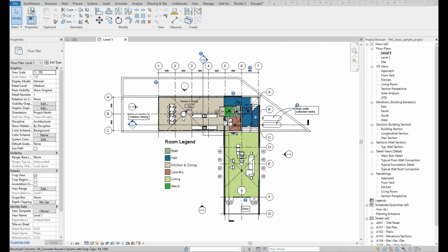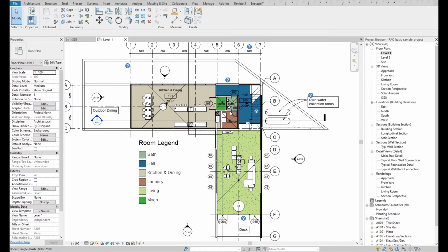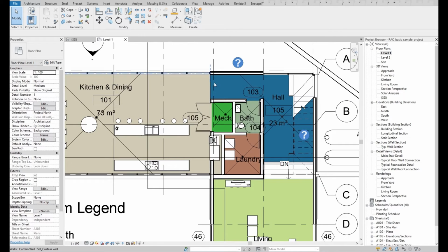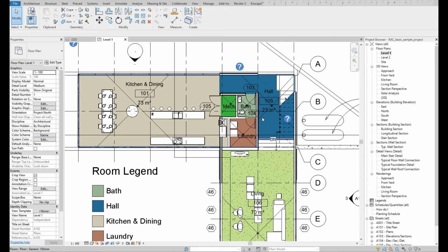Now we are using this sample Revit file of a residential model by Autodesk and show how to use the design option. So imagine if you were working on an existing project, then all of a sudden the client wants to explore the layout of the toilet. But in your mind, I don't want to scrap this model and wanted to create a separate layout. The design option feature is perfect for this kind of situation.